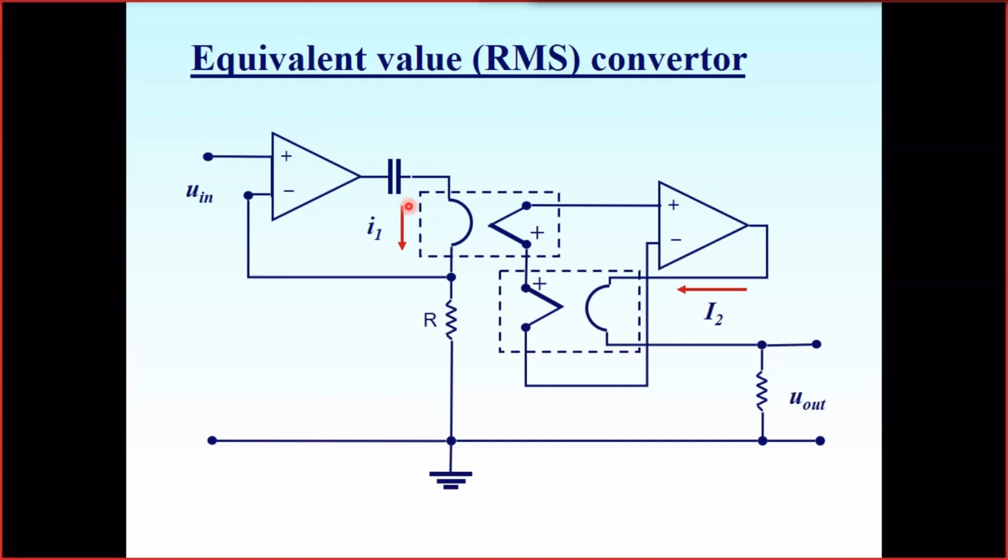To convert voltage into current, not just by applying this voltage over the resistor, we keep this current proportional to U in divided by R. So the current is more or less stable. This current causes the electromotive force to appear here. The electromotive force on this thermocouple will be higher than the electromotive force on this thermocouple. So the total voltage here will be positive.